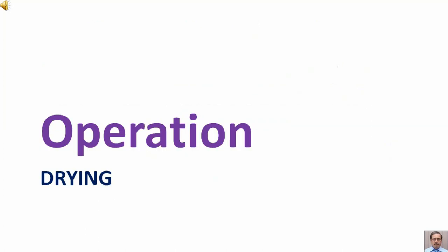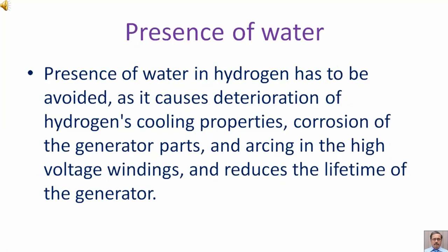Operation sub-issue: drying. Presence of water in hydrogen has to be avoided as it causes deterioration of hydrogen's cooling properties, corrosion of the generator parts, and arcing in the high voltage windings, and reduces the lifetime of the generator.